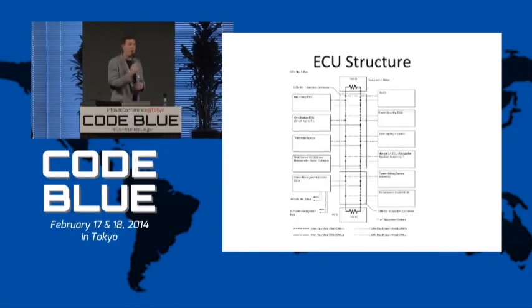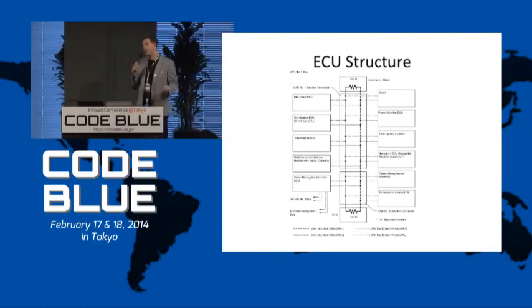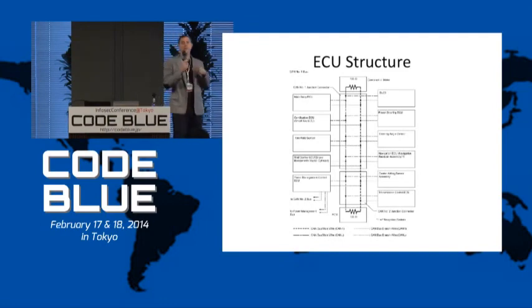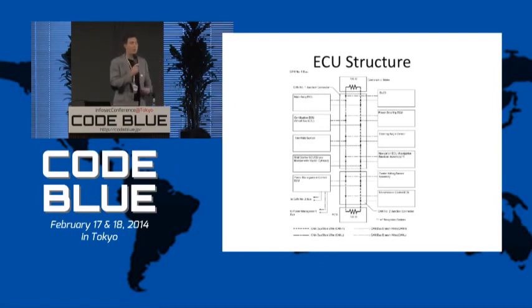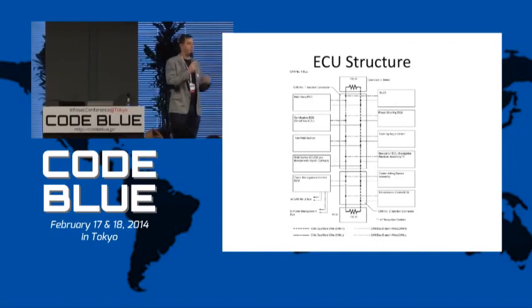They have really, I guess you could call almost a token ring structure. So the CAN bus is set up so every node that's on a bus can communicate with every other node. They're always periodically broadcasting information, right? For example, a computer that broadcasts the speed will always be broadcasting the speed perpetually, so many times a second, right?